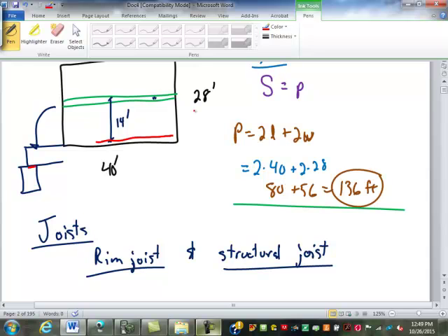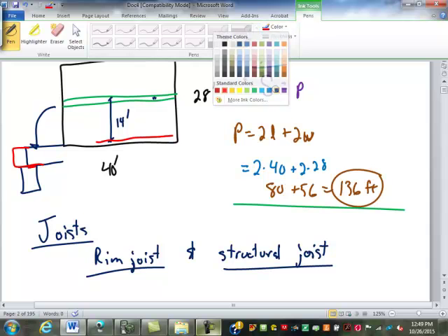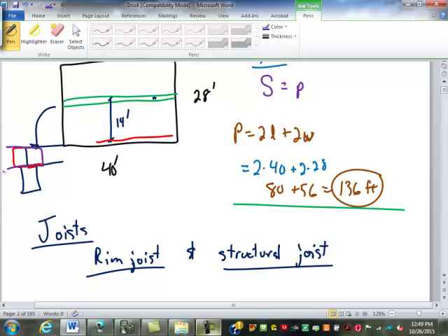The joists? Yeah, they sometimes run past like this, and then the ones coming from the other direction will run past this way, and they overlap each other. Now, there is a maximum overlap you want on your joists. Sometimes it depends on span. Usually they say 8 inches, 12 inches, depending on who you're talking to. Yeah, overlap between the joists. The reason for that is if they overlap too much, the floor always sags.